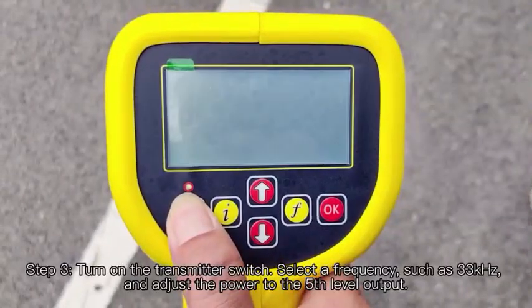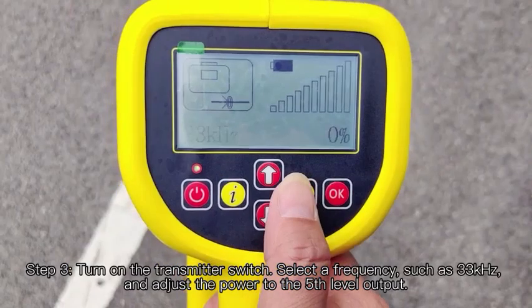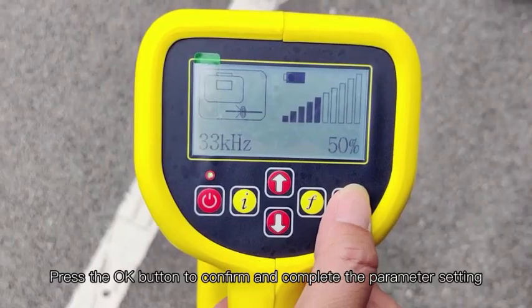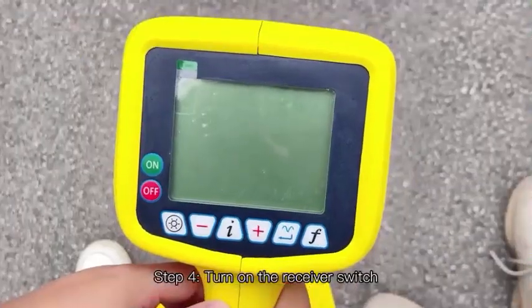Step 3. Turn on the transmitter switch. Select a frequency, such as 33 kHz, and adjust the power to the 5th level output. Press the OK button to confirm and complete the parameter setting. Step 4.